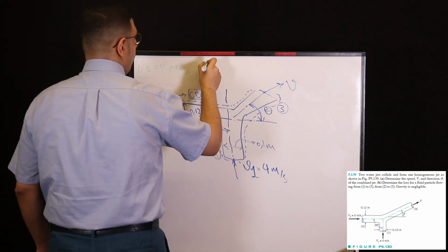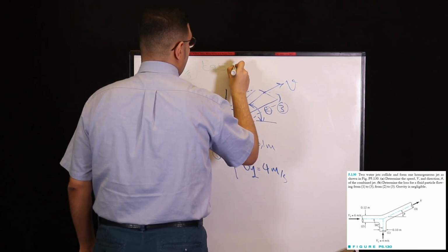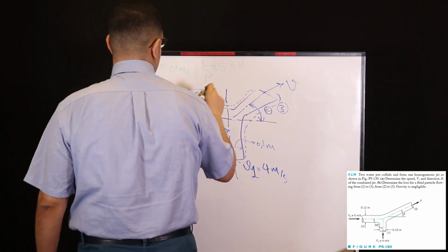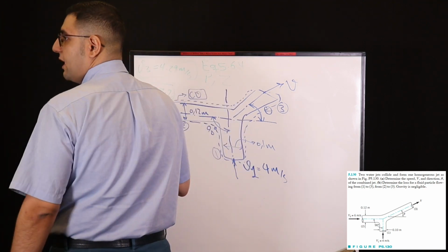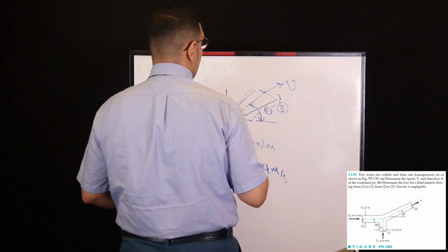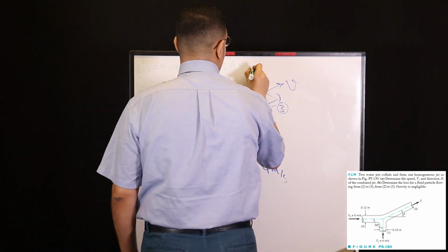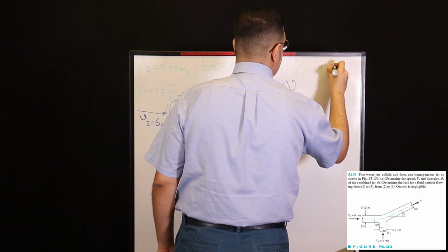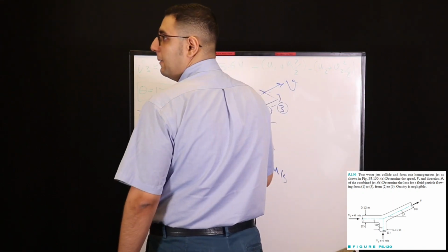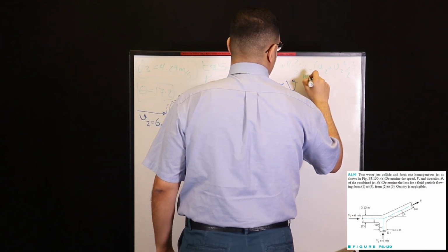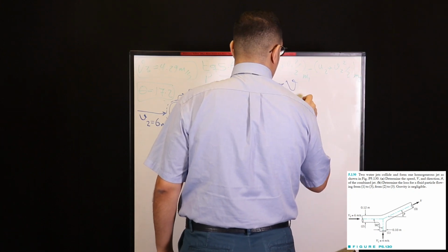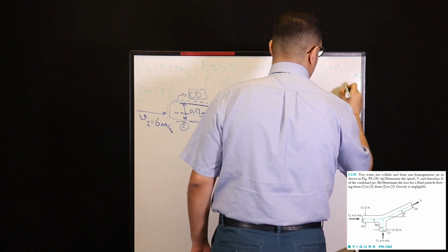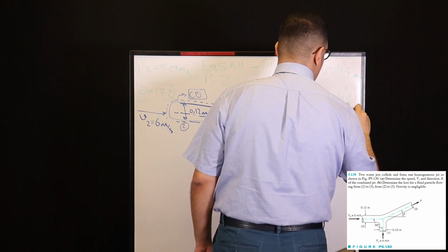Using equation 5.64, neglecting the pressure as well as the elevation, we can have the available energy associated with the flow of the control volume as minus U1 plus V1 to power 2 divided by 2, minus U2 plus V2 to power 2 over 2, times the mass flow rates 1 and 2, plus U3 plus V3 to power 2 divided by 2 times M3 dot.